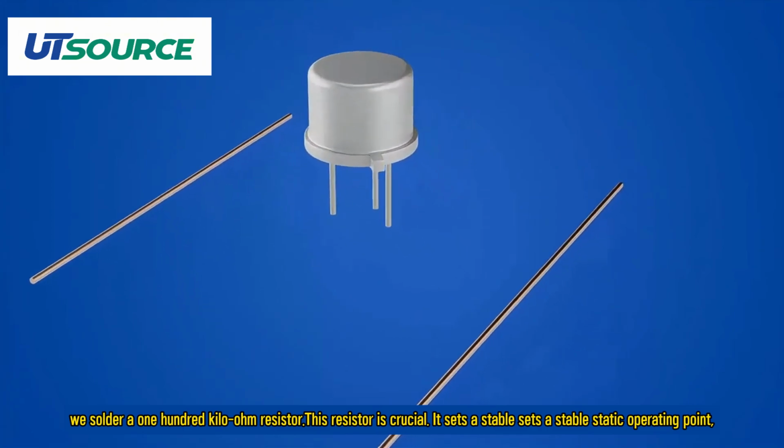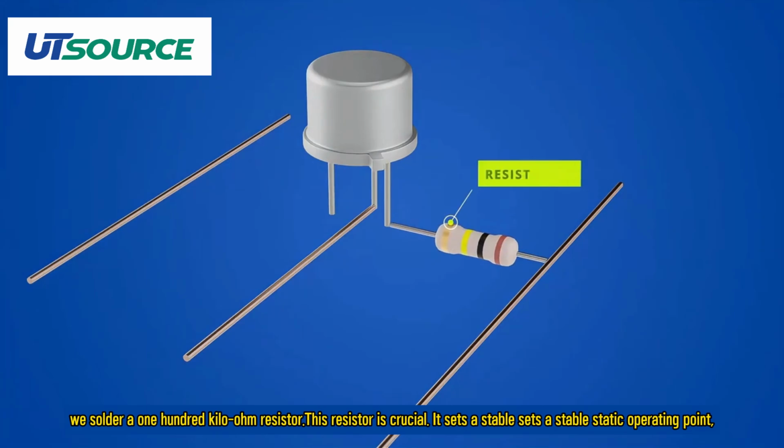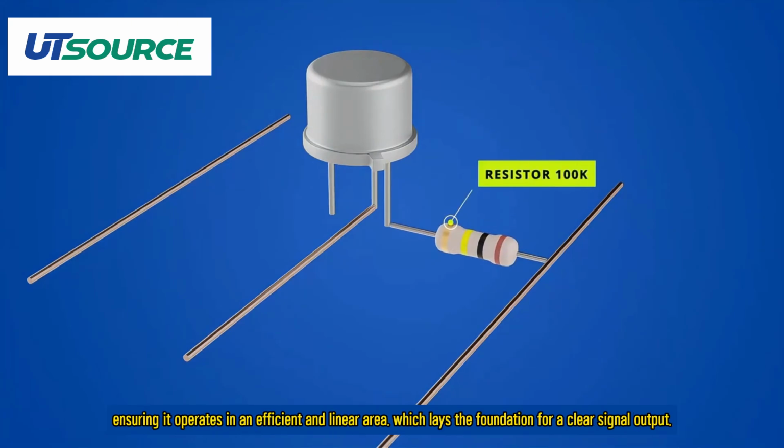we solder a 100 kilo ohm resistor. This resistor is crucial. It sets a stable static operating point, ensuring it operates in an efficient and linear area, which lays the foundation for a clear signal output.